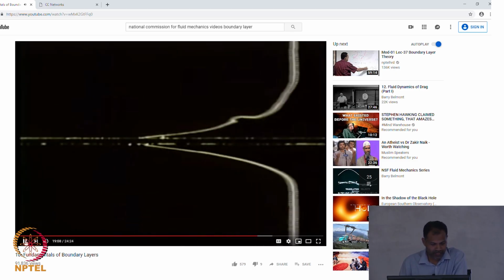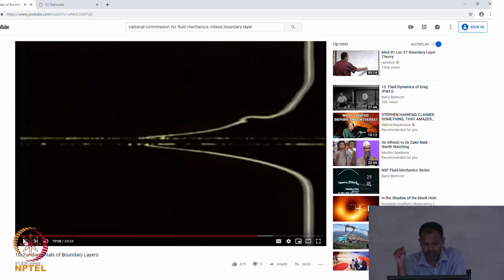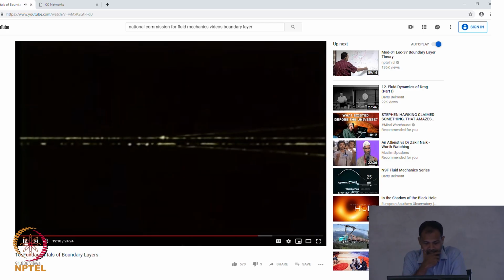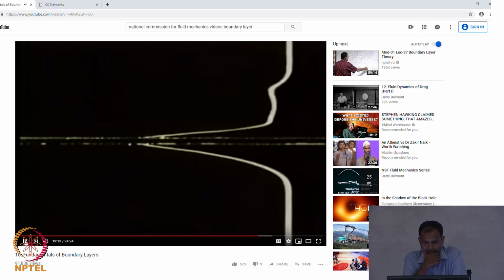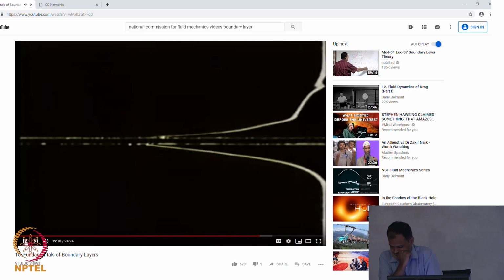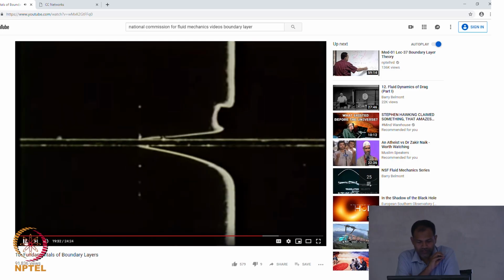Okay, so you can see here also they have done the same thing. You have a plate above, they have made it turbulent, below it's laminar. So in the laminar case you can see that boundary layer, and up it will be all fluctuating velocity field. I think we'll draw a little more. They will show you a few snapshots of various profiles. So, this is the effect of the fluctuations in the velocity field in a turbulent flow.